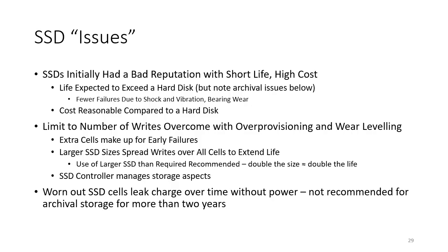The other thing we get is wear leveling. As I mentioned, what you have inside the SSD is a controller chip, and the controller chip spreads the writes over all of the cells to extend their life. So unlike with a hard disk where you can write to each magnetic cell indefinitely, or to maybe an SLC where you've got 100,000 writes per cell, you've got a smaller number of writes, but what you do is you just spread that number of writes over a wider area, and that effectively improves the life of the disk by a large amount. My recommendation is to look at an SSD and also buy a larger SSD than you need, because that will also further encourage the spread of writes over all cells and further extend the life.